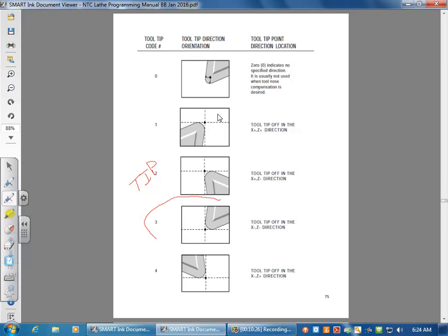This is going to be your most common, turning the outside of your part with your tool cutting this way. Now this is for a slant bed lathe like we have for our CNCs. This one here would be for like your manual or what they call tool room lathes, where your tool is standing on the same side you are of the part. But this is done here for us. We use that in boring. So if you could picture that tool inside of a part, cutting out the bore with that tool coming from the back. But this is where our normal outside turning is.